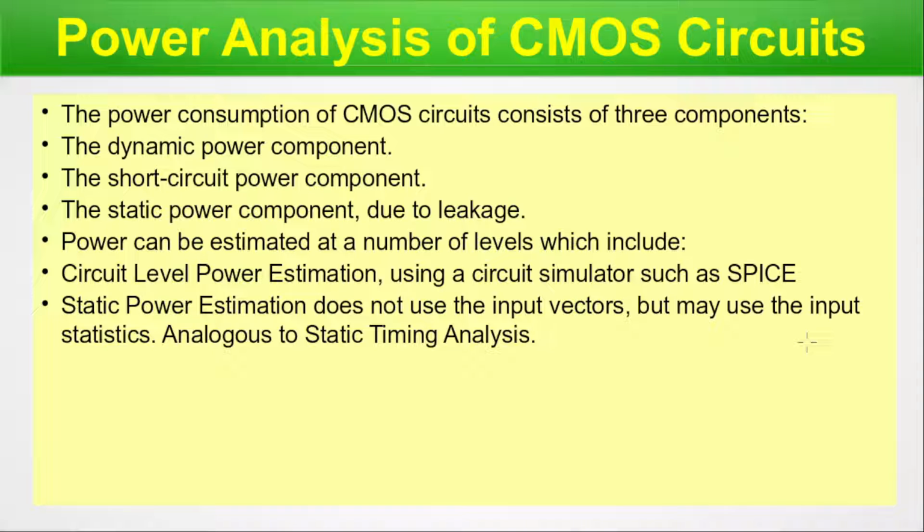That means the time marker proceeds, you give a start time, you give a finish time, and all the values for all the nodes, the KCL, KVL, everything has to be calculated, and according to the power calculation formula, the power has to be calculated. That is the dynamic one. Whereas in static mode, you have some predefined or pre-logged data based on which you calculate the power. That is the static power estimate.